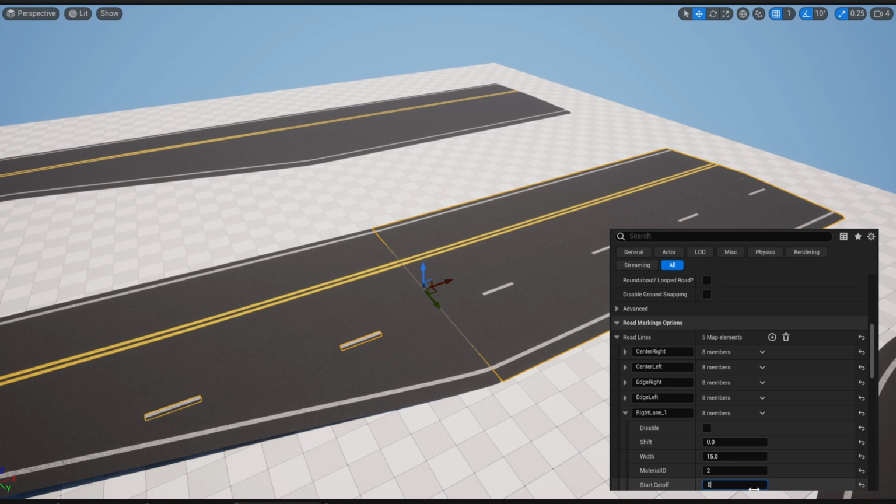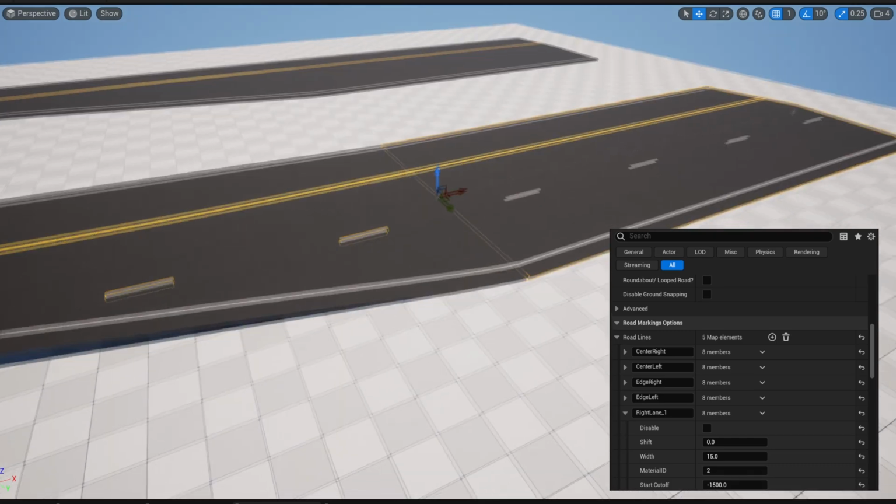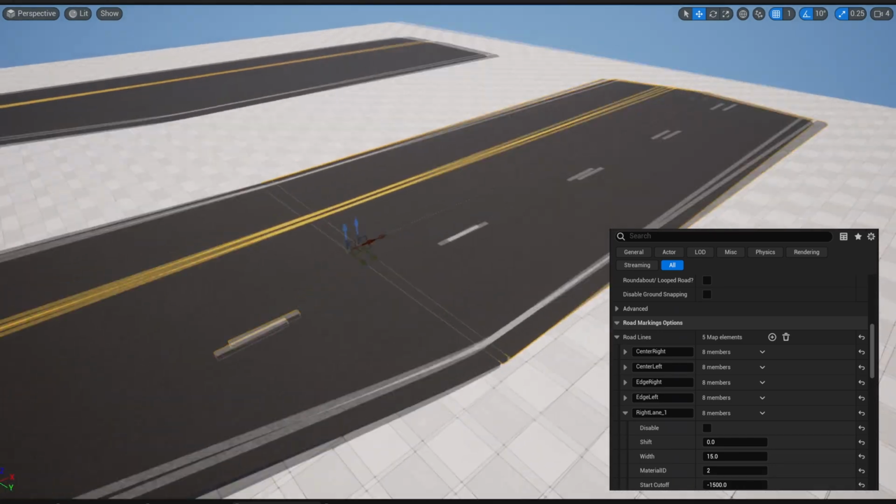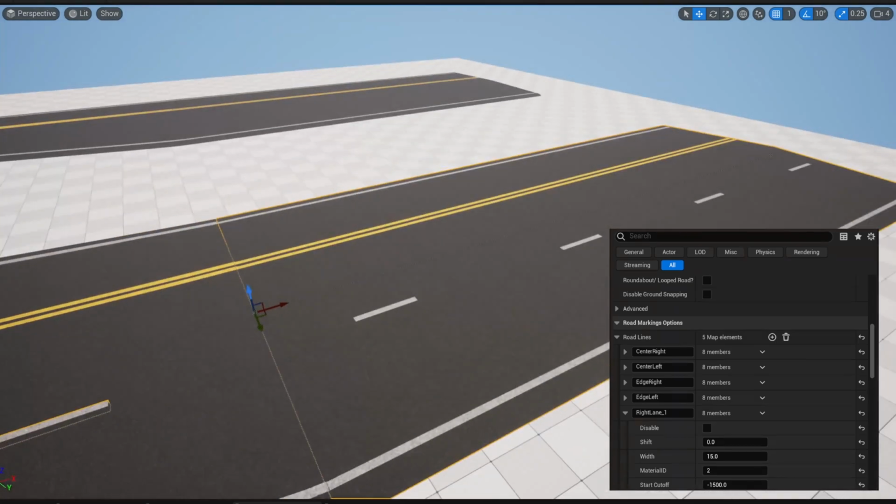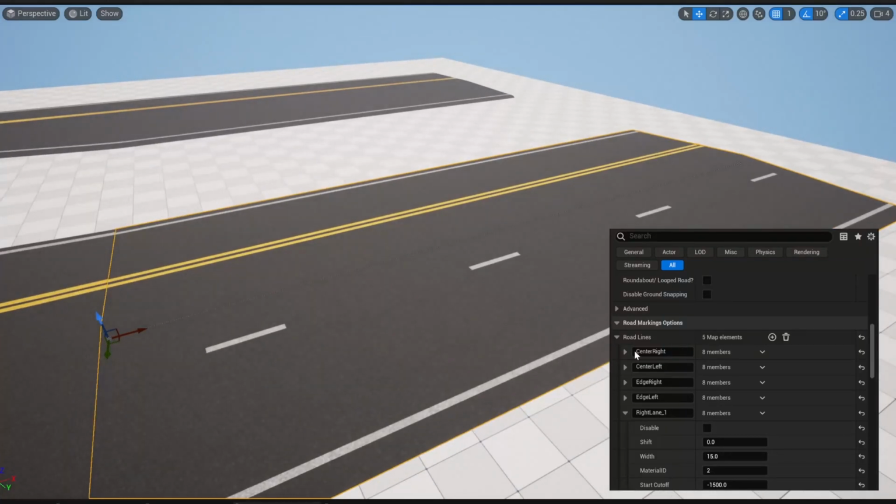There are a couple of limitations to it being negative though, and that is that I can only go backward in a straight line and the elevation needs to not shift too heavily for the portion of the line that is going backward. This is a limitation for the time being, but we are working to make the backward spline follow the connected road spline to fix that problem.